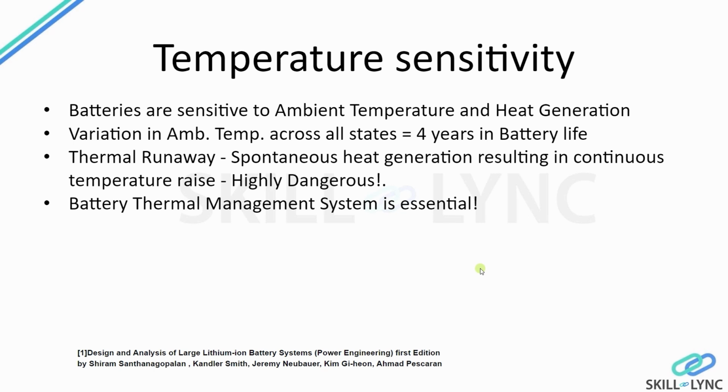In other words, you need to make sure that while designing a battery pack, the temperature non-homogeneity is as low as possible. Thermal runaway, I think we have already talked about that a bit. So the above points essentially let us know that a battery thermal management system is essential for electric vehicle applications. Especially when you have larger battery packs with more cells, you need to make sure that whatever cooling strategy you use results in lower non-homogeneity of temperature amongst all these cells.